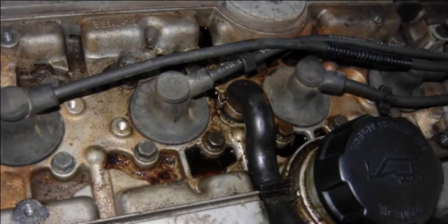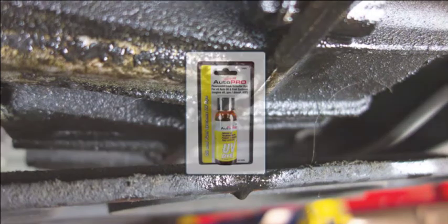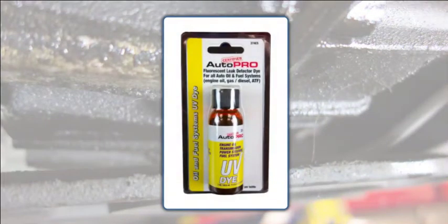Oil leaks can occur in small engines. These leaks can cause a misfire DTC and coil failure. An oil leak that is difficult to locate can often be diagnosed by using leak dye. Add the dye to the engine oil. You may have to ask the customer to use an ultraviolet light to locate the leak. This dye can also be used for power steering, transmission, differential, transfer case, and fuel system leak diagnosis.